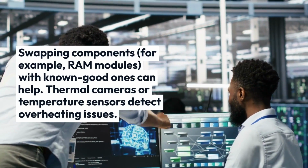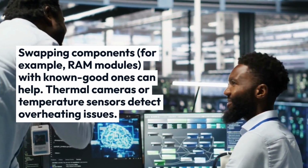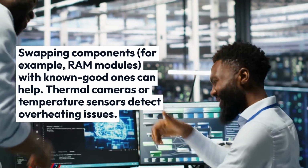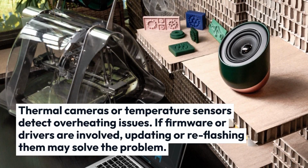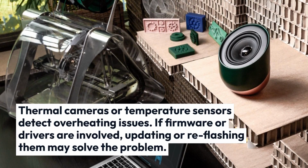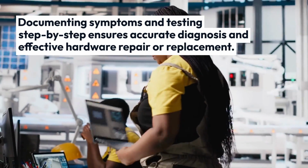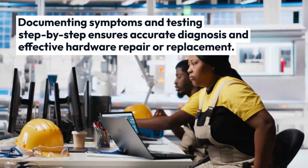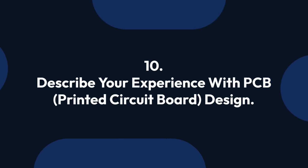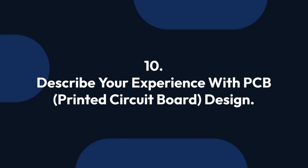Swapping components, for example, RAM modules, with known good ones can help. Thermal cameras or temperature sensors detect overheating issues. If firmware or drivers are involved, updating or reflashing them may solve the problem. Documenting symptoms and testing step-by-step ensures accurate diagnosis and effective hardware repair or replacement. 10. Describe your experience with PCB, printed circuit board, design.